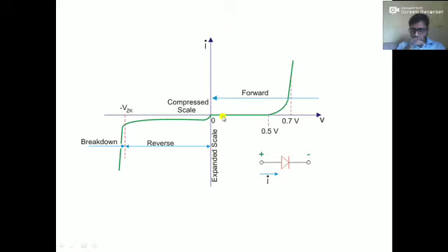At a certain value of the voltage, the current could not increase, and up to a certain value, when you increase the voltage, the current is suddenly increased. But when you apply it in the reverse bias condition, this VZ is indicating the Zener breakdown knee voltage, VZK.